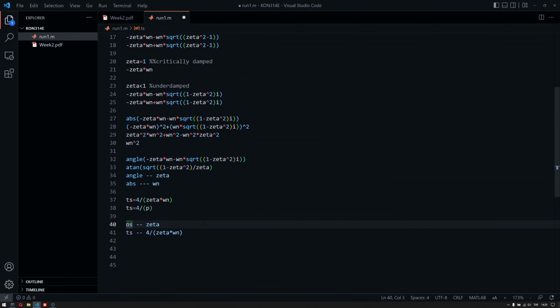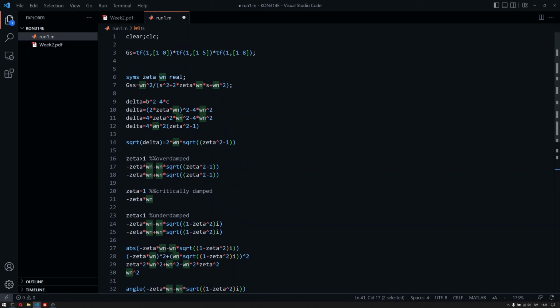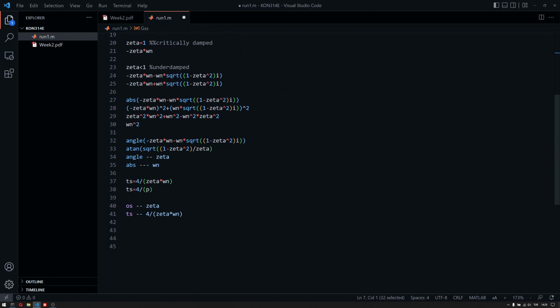So what I mean by that is, let's assume we have an overshoot value, and let's say overshoot is equal to 0, we pick zeta equals 1. At that point, we will just pick an omega n value of 1 in this case, since we want to have 4 seconds of settling time. So zeta is 1, omega n is 1, all is well at this point. Now, if we have zeta 1, omega n 1, you can just directly plug it into this definition. You will see that it will be 1 divided by s squared plus 2s plus 1. And that's basically it. You should aim for this transfer function if you want to have this settling time and overshoot values. So that's basically the thing that we are trying to do.